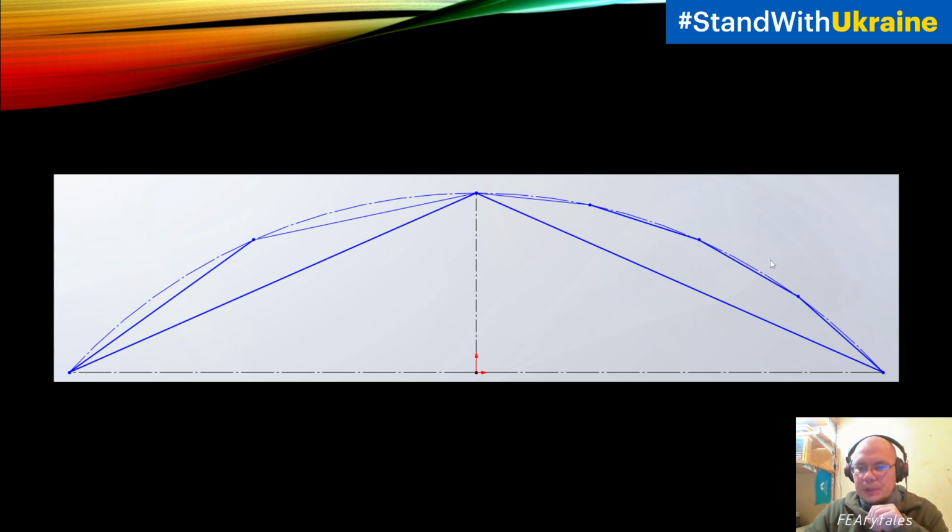If we take a look at this arc, it can be a thin arc, it can be an arc from a circle. It can be part of a parabola. And we can see that it's a deformation of our beam plate when it's fixed here with displacement and forced here. Or we can take a look only at this part and say that we have full fixation here in the middle and force on this end or this end.